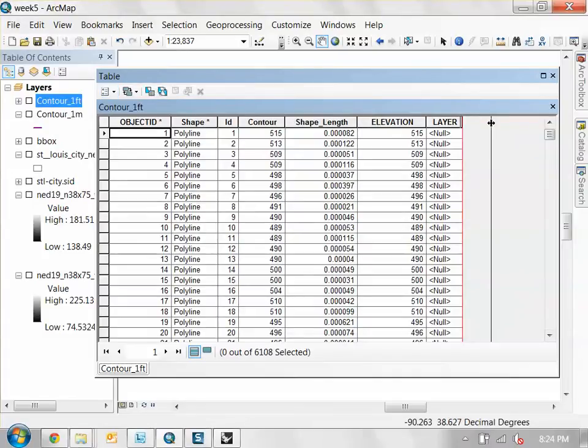Whatever word you put in this layer field is going to set that layer automatically when you bring it into Rhino. So you can set that layer to, say, your land use or your road type, and automatically in Rhino, it'll split all that information into its own layer, so it's easy to turn things on and off, and it's not just one group of things. But for this study, we're just going to split this elevation into major and minor contours.